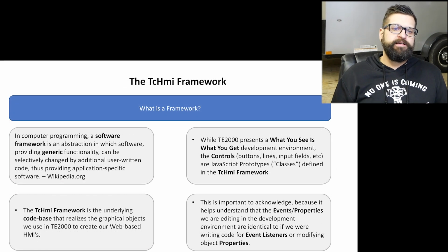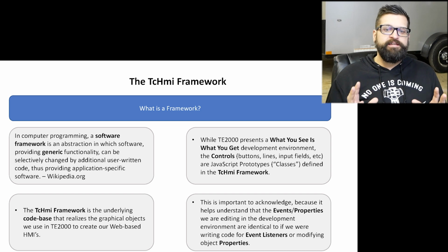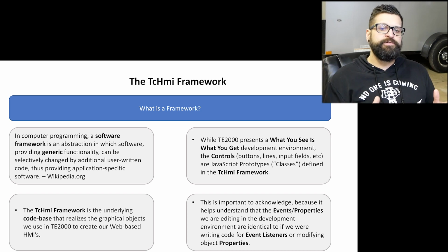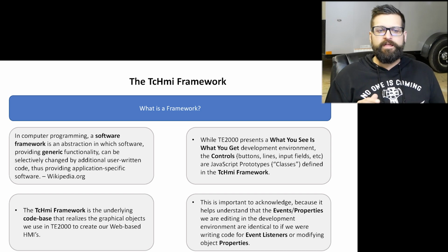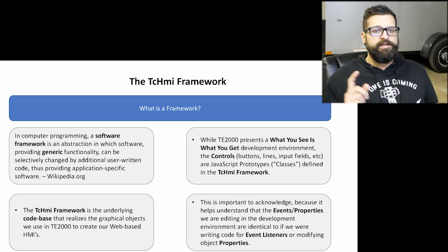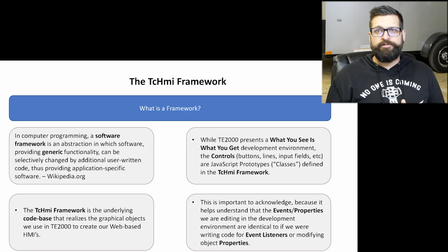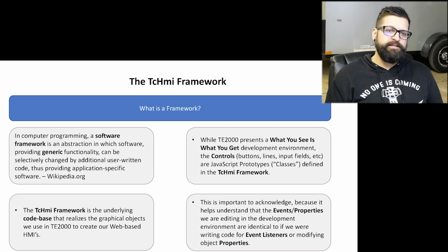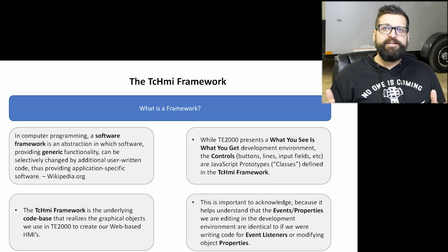Okay, so something that's going to come up again and again is the TcHmi Framework. When we start looking at controls, and a control is any object, any element that you're going to add to an HMI in the engineering environment, we call those controls. So buttons, input fields, keyboards, any of those on-screen devices that have some functionality, that's a control. And then there are subsets of those, like a user control, which is a type of control that's customized by the user. That's where we get into templating, and we'll look at that in a little bit down the road. But all of those live under the umbrella of the TcHmi Framework.